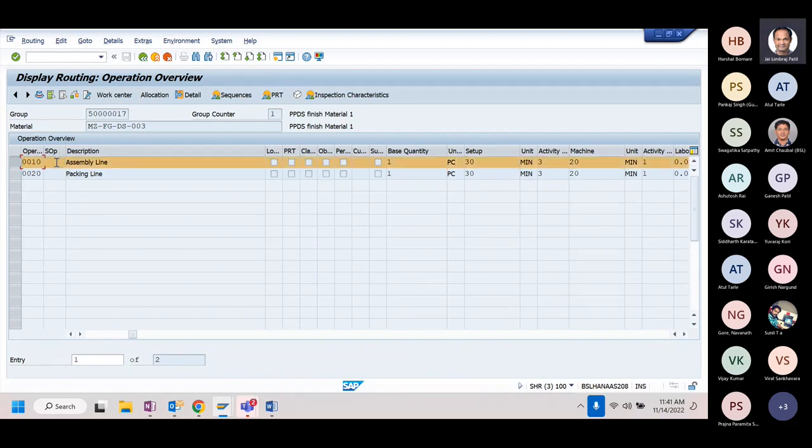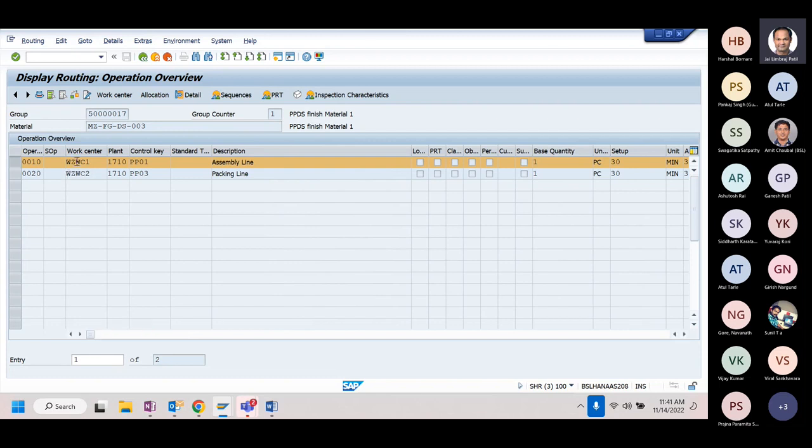in the work center that was C1, and then on that work center we will need a setup time of 30 minutes and then a machining time of 20 minutes. Between this setup and machining, setup is fixed and machining is quantity dependent. What I said, fixed and quantity dependent, is determined not from this routing, but from the setup that we have within this work center.